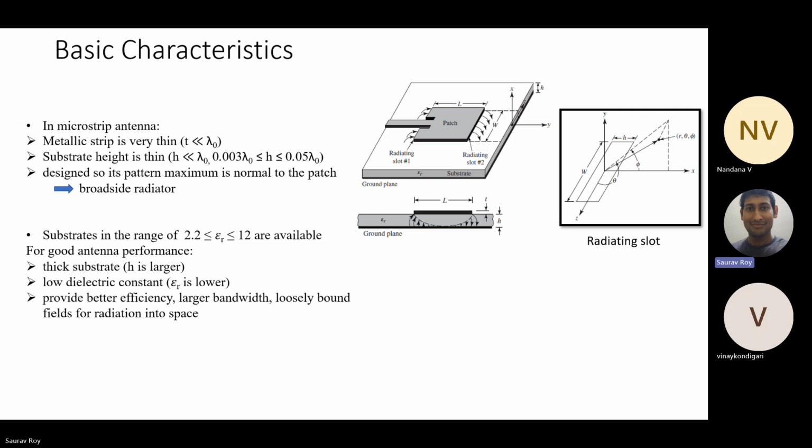But now you see how this microstrip antenna is considered geometrically. Understood, right? The top picture and bottom picture, top view and side view. Do you understand how they are seen? See the side view. The thickness is T, small t, right? This thickness will be there on the four sides of the patch, right? So those are called slots of the patch antenna. And you see the substrate and the ground plane there, right?